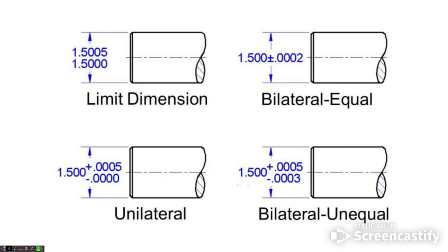Although in most cases, we'll talk more about proper fits for pins and holes as we go through. And then there's also the bilateral unequal type tolerance here as well. Now, all of this, of course, is terminology that draftspeople and designers might need to be familiar with and talk about. To be honest with you, though, I don't know of a whole lot of machinists out there on the shop floor that are actually referring to these as bilateral equal or bilateral unequal, unilateral, or are these actual names. At least not in my experience.